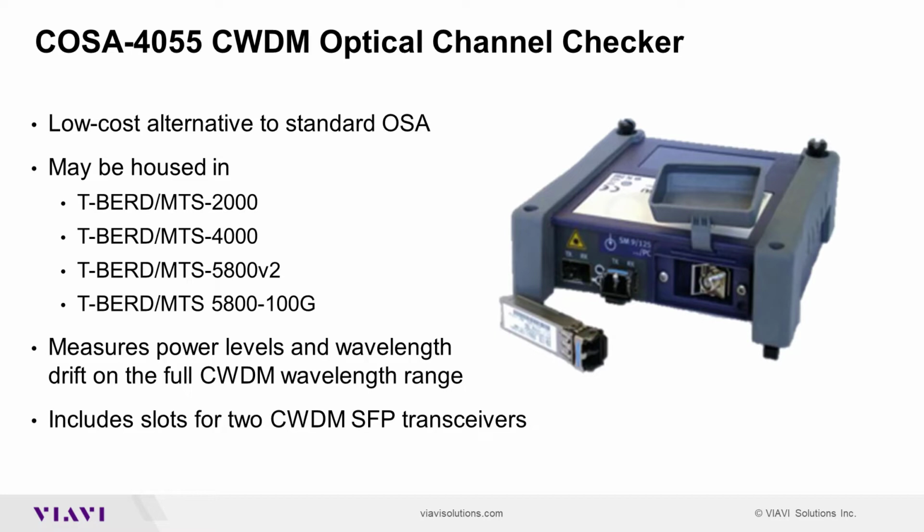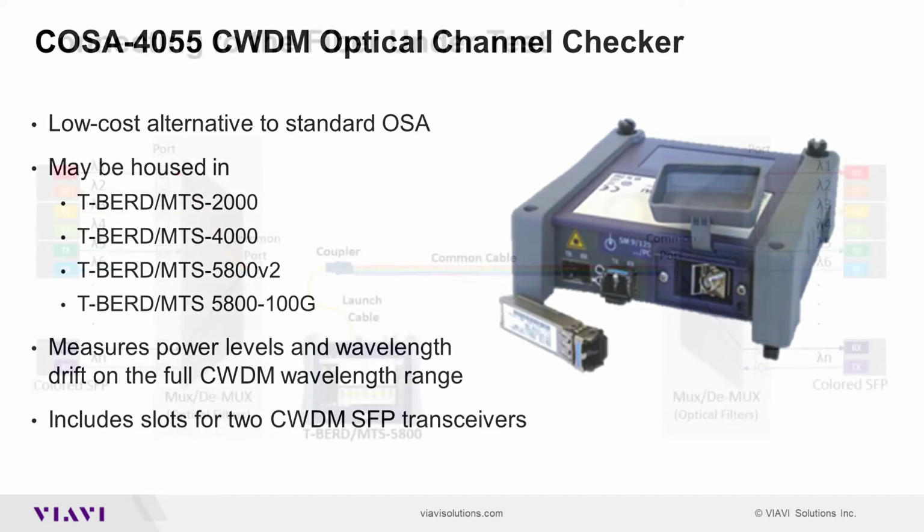In addition to the test port, the module has two integrated SFP slots. A CWDM optical transceiver may be connected to either or both SFP slots. Once inserted, the SFP is automatically activated for use as a CWDM light source.